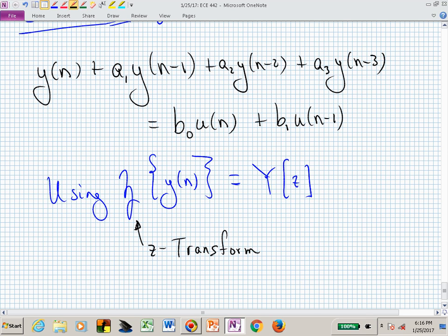And you might say, what is Y? Well, we've actually implicitly buried the sample period. Somebody might write this as Y of nT. Sometimes we have the T shown, sometimes we don't. But it's Y of n. To be cleaner or easier to write, I may just write Y of n, which is what I did in my linear difference equation. But you would have to be told if it was indeed something that was sampled, if it wasn't a fundamentally discrete time relationship, now you would have to know what is capital T. But a lot of times it's not shown in the equation.